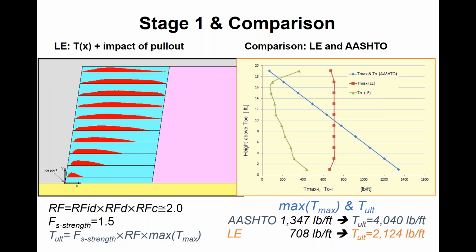But maybe that's underselling what's also implicit here in the fact that we're also directly accounting for pullout at the rear end in this one stage. So basically it's doing your multiple little modules or components for internal stability in one and giving you both connection demand at the face and that Tmax, which might not always be the same Tmax that you get from your trial and error process.